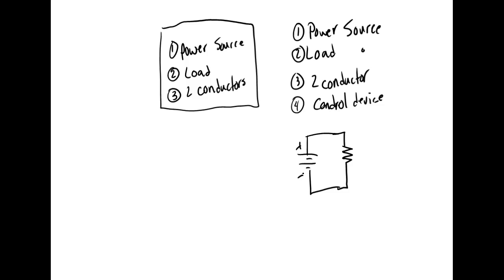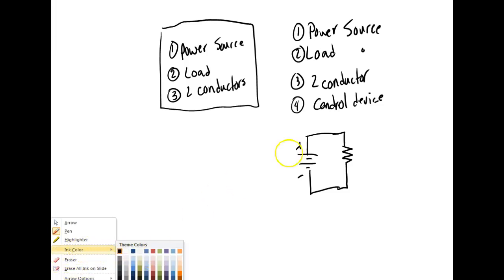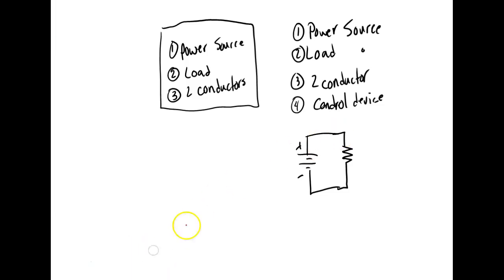You could choose which one is common. And of course in PLCs we refer to it as sinking or sourcing. Now normally what you said was probably right, because normally when we draw a schematic, okay, y'all listen to this, this is what electricians refer to as the hot side, because it's drawn on top, right? And normally the common is drawn on the bottom.